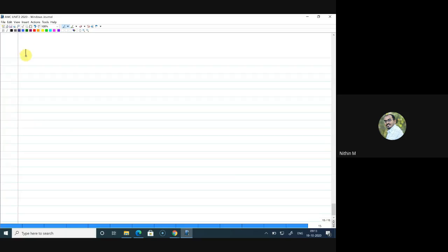I'll just summarize the current equations once again, because based on this only we will progress in our studies. So we know that collector current Ic is Is times e to the power of VBE by Vt, where VBE is the forward voltage at the emitter base junction, Is is the reverse saturation current, and Vt is the volt equivalent of temperature.